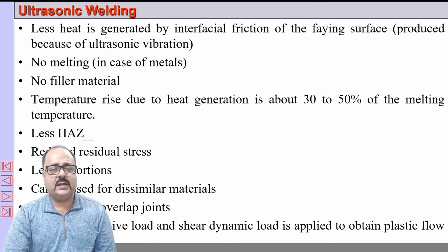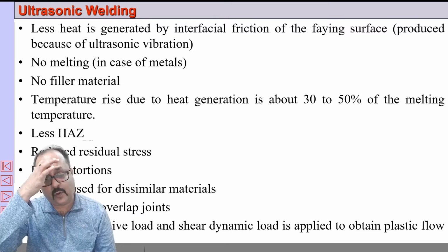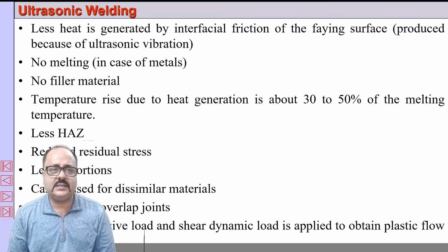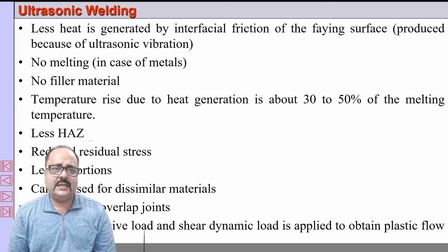Let's start with the salient points about ultrasonic welding. Here the heat generated is less, and it is generated by interfacial friction of the faying surface. Now how is this friction created? This friction is created by the ultrasonic vibration, and the heat generated is very less, and there is no melting that takes place,